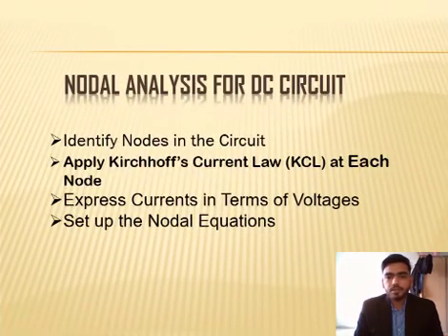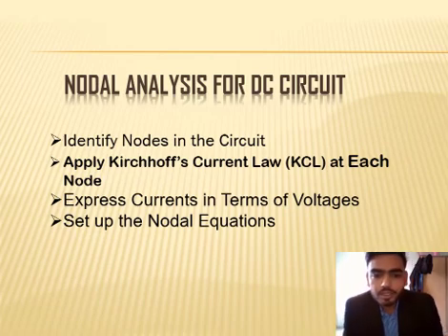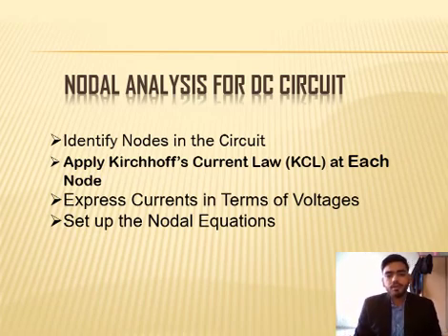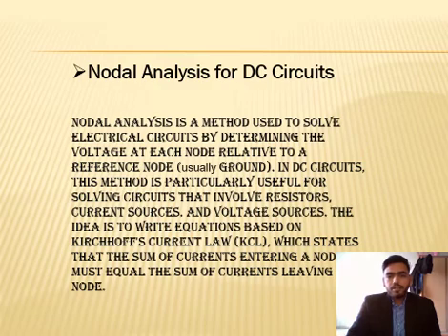Node analysis for DC circuit: introduction. Identify the nodes in the circuit. Apply Kirchhoff's current law, KCL. For each node, express the currents in terms of voltages. Then set up the node equations.